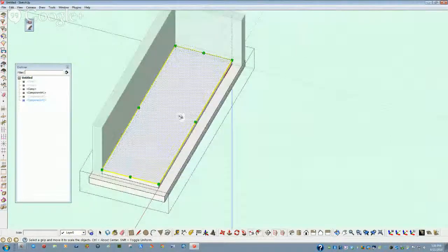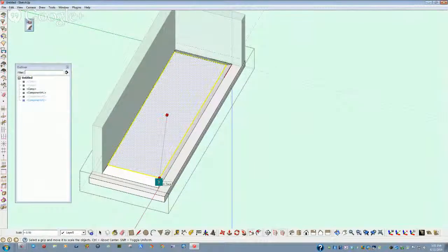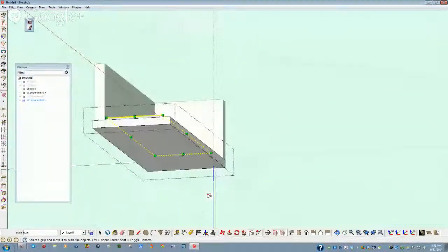And there are several ways to handle this edit. I'm just going to do one easy. I have several videos out there on how to do it, and I'll answer questions again anyway. I grabbed one corner. You can see it says uniform scale about opposite point. Well, I don't really want that. I want to hold my control key down, and then it says uniform scale around center. I just let it fall in a little bit.